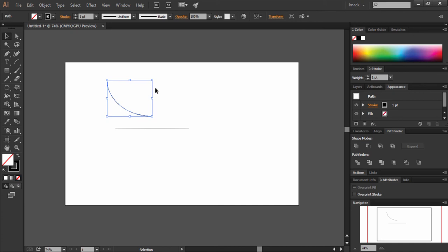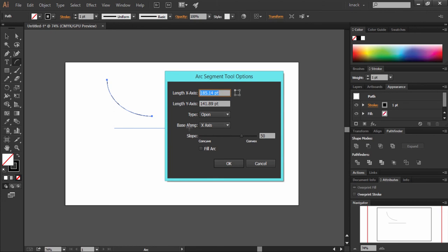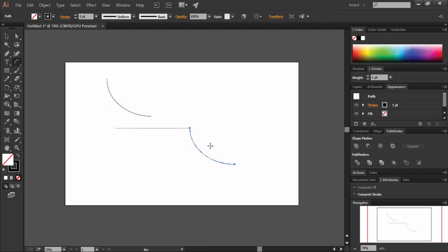Let's do a practical. I'll come over this point. Notice that the smart guides are telling me that I am over the anchor point. I will click this point to open the Arc Tool dialog box. Don't bother about other options, and see if I choose the upper left corner reference point, the arc will originate from this point, locating it as the upper left corner point of the bounding box. Arc is drawn and I select the black arrow to view its bounding box.